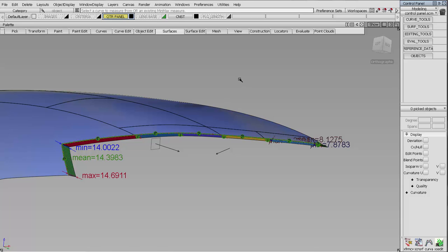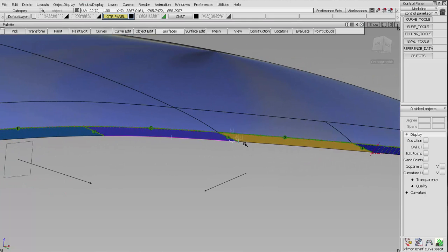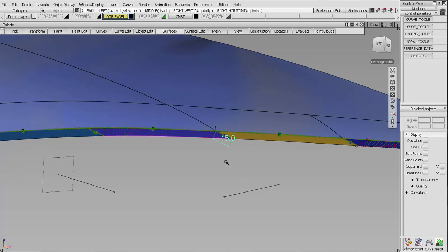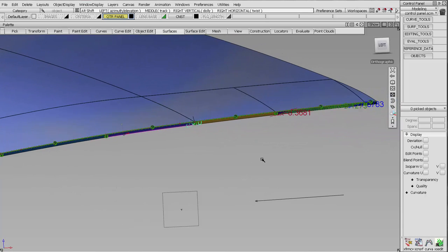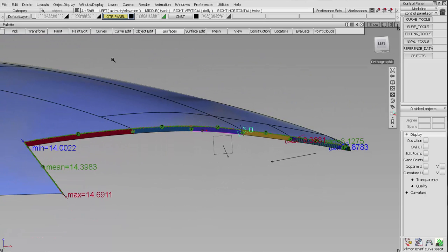So where's the 15 coming from right now? If we measure the distance, okay, so just 2 points, and we measure from the end of flange to the start of flange, that's 15. So those lines are created in the direction of this die view. That's the distance that's being measured and calculated. So we need to switch that up.